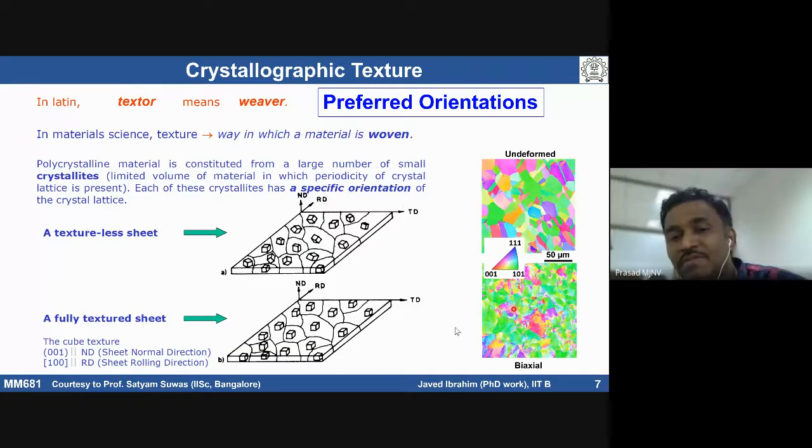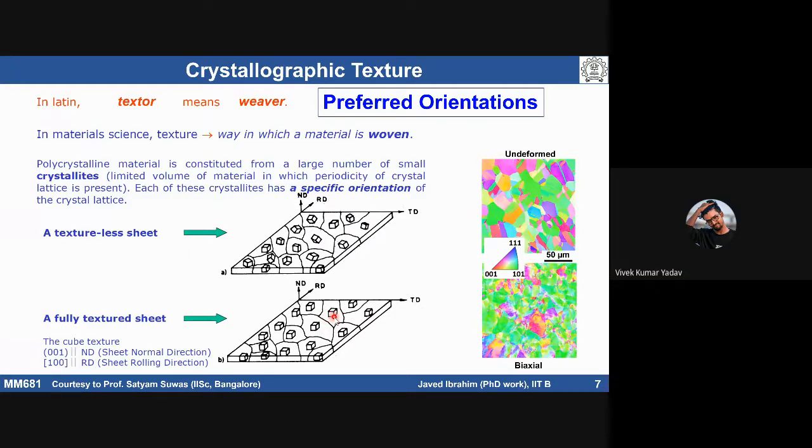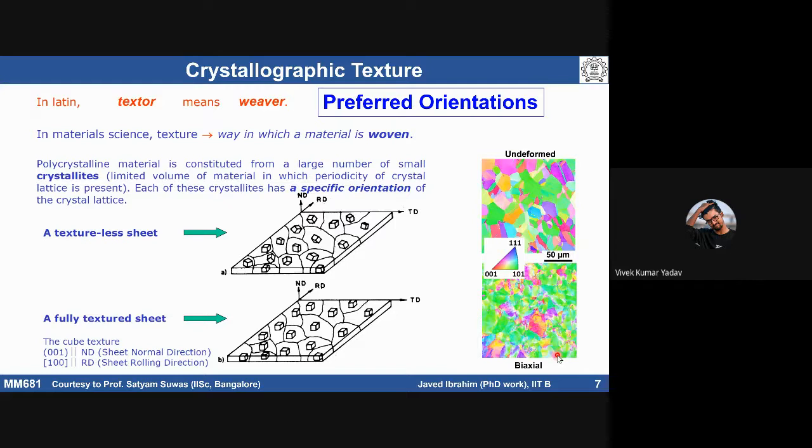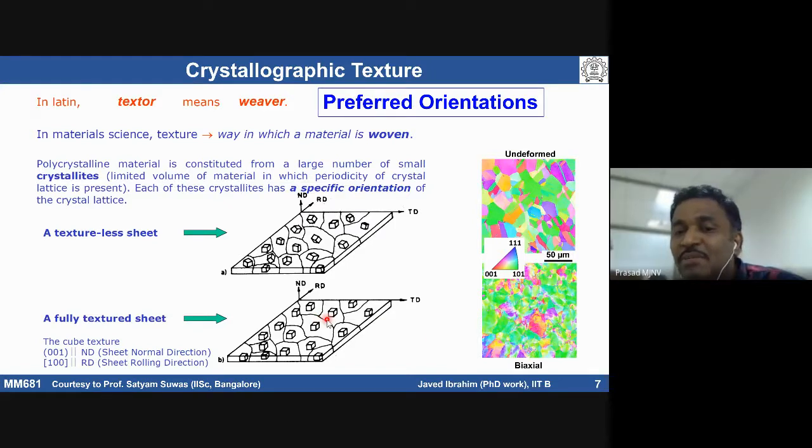No, see, even if it is the same, there will be small variations. Some boundary is going to exist during deformation. Look at here, it's very hard to identify a boundary. But they will exist. There will be some low angle boundaries. Because of the twist, we may see some kind of rearranged boundary also getting rearranged.